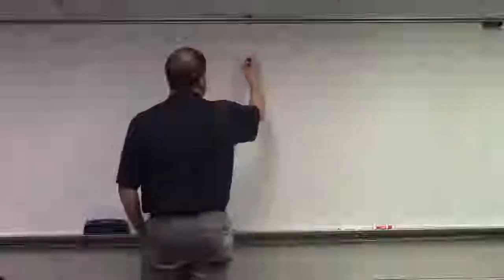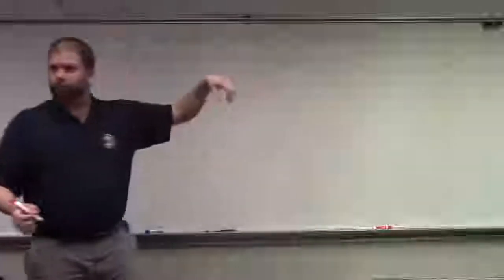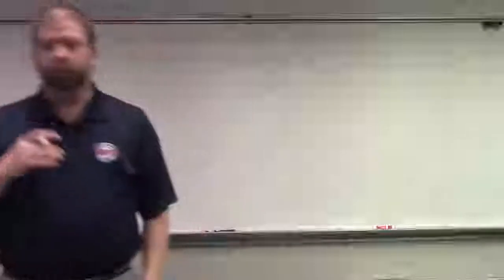to determine M sub U, right? What does that mean? Our ultimate moment, right? If we combine the loading factors with our dead load and live load, it tells us that ultimate loading condition that we need to be aware of.